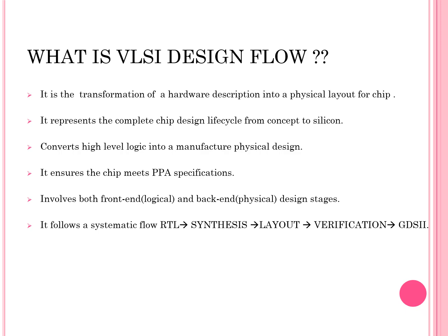Now let's talk about what exactly VLSI design flow is. VLSI design flow is basically the transformation of hardware description into a physical chip layout. It represents the complete life cycle of a chip, starting from an idea or concept and ending as a silicon that's ready for manufacturing. It converts high-level logic into a manufacturing physical design, ensures that the chip meets all PPA specifications, that means performance, power, and area requirements.